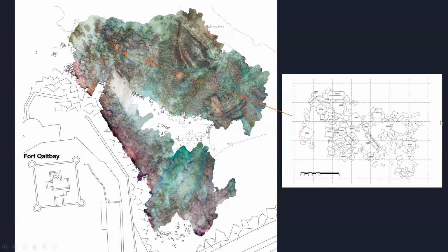Like you can see, also 2D drawing, we can remap the whole site based on the orthorectified image. For the people who don't know what an orthorectified image is, it's an undistorted 2D image. And we can take the X and Y dimensions from it, and the dimensions are 100% accurate, same as I'm doing on the real site. So I can take the X and Y dimensions from this map without diving in the site anymore, so I can redraw the whole site.